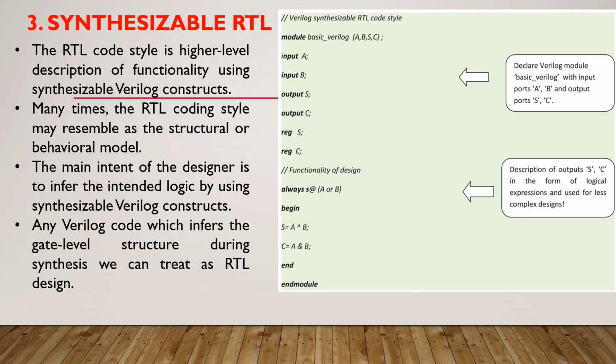The next one is synthesizable RTL. It is also a higher level description. It uses synthesizable Verilog constructs, because Verilog supports both synthesizable as well as non-synthesizable constructs. But here the RTL code is using the synthesizable Verilog constructs.